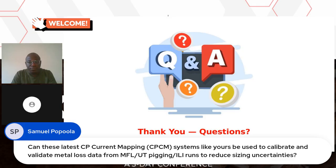So normally, you can say, for this particular location where we are having thickness losses, what potentials are we measuring from our CP system? Is it protected or is it unprotected? Between your MFL or UT runs, you probably do it maybe every 5 years or thereabouts. So within those 5 years, what has been the potentials of this region, if I compare with what I'm seeing on my MFL ILI runs?